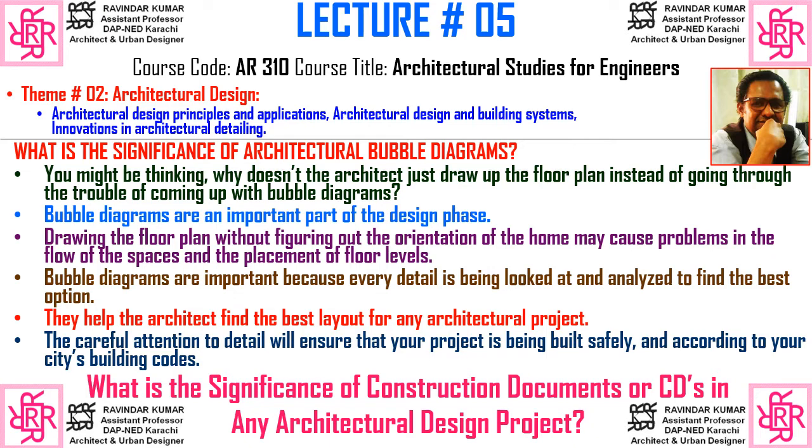What is the significance of the architectural bubble diagram? You might be thinking, why doesn't the architect just draw the floor plan instead of going through the trouble of coming up with bubble diagrams? Bubble diagrams are an important part of the design phase. Drawing the floor plan without figuring out the orientation of the home may cause problems in the flow of these spaces and the placement of floor levels.